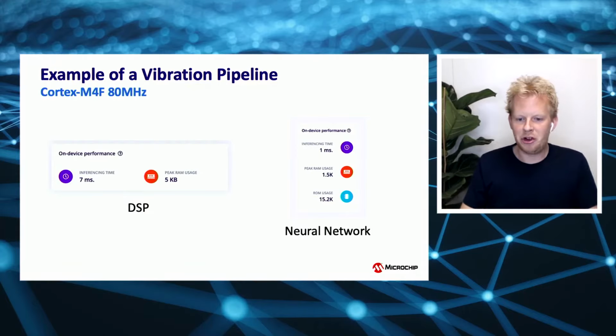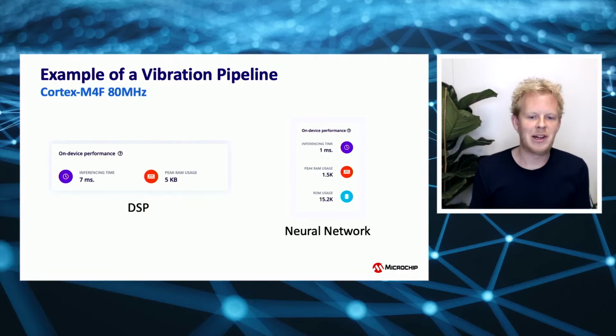Afterwards, we have features, the same features that you might previously have used to do some basic calculation on that signal. So the height of peaks on FFT length, power spectral density buckets, and that we can feed into a neural network. And because we already did lots of pre-processing, we've done lots of filtering beforehand to make sure that that is actually clean data, we can have a very small neural network to the end classification. So we can run this whole pipeline in 10 milliseconds with 6K of RAM. And that applies to higher resolution data as well.